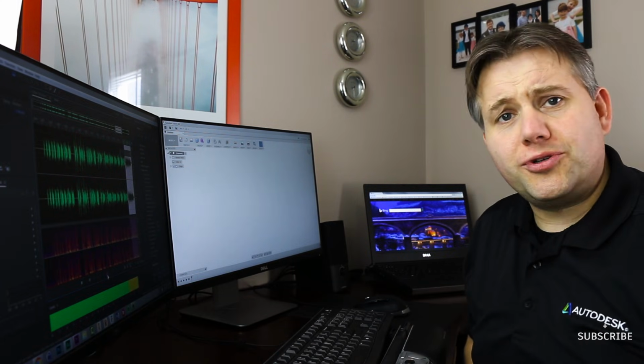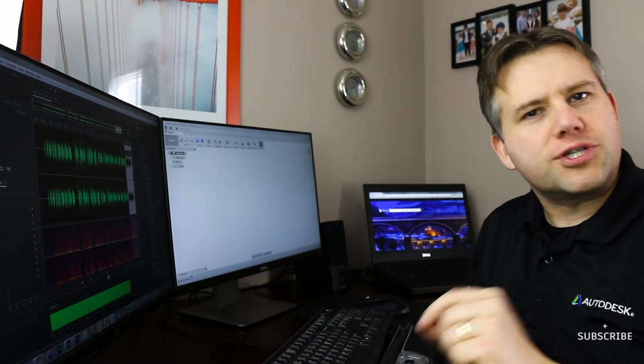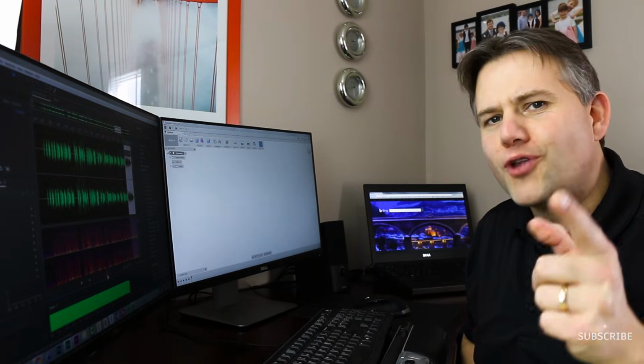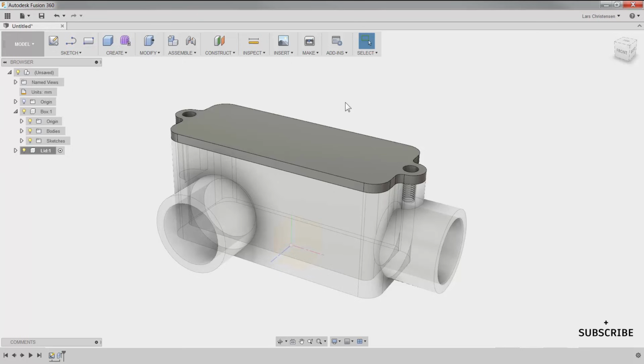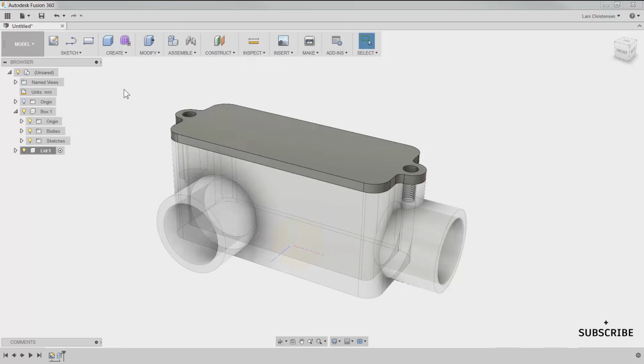Now, the feature I want to show you now is, I would say, a little advanced. So if you don't get it, just scroll back and rewatch it. But this is definitely very powerful knowledge to have, I think. I talked about in the beginning that we're always sketching either on a sketch or a plane. Well, sometimes you don't have that sketch or plane to sketch on, and you can actually create your own. So up here, we have all different kinds of plane tools that can help you create a plane so you actually have something to sketch on.